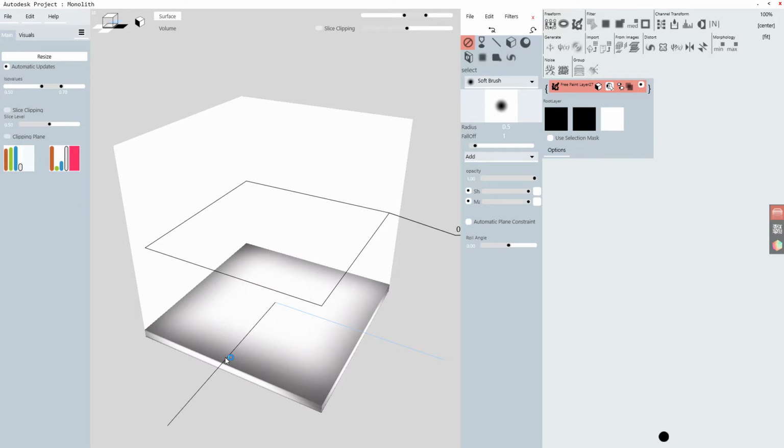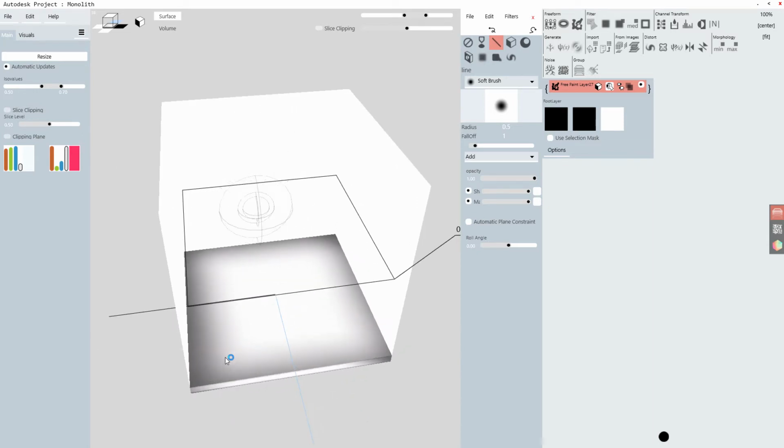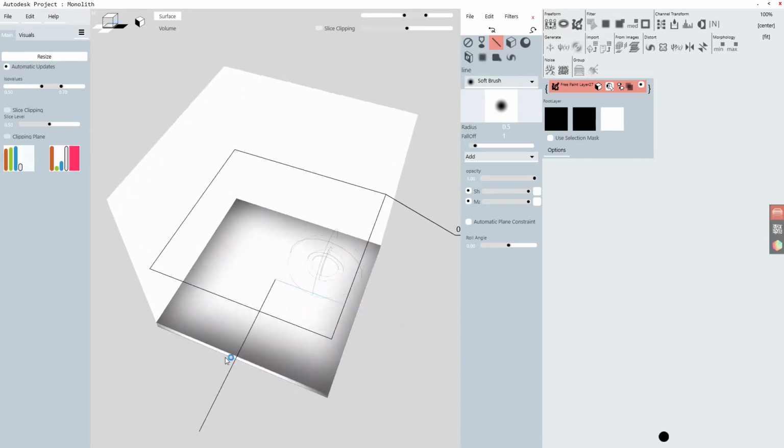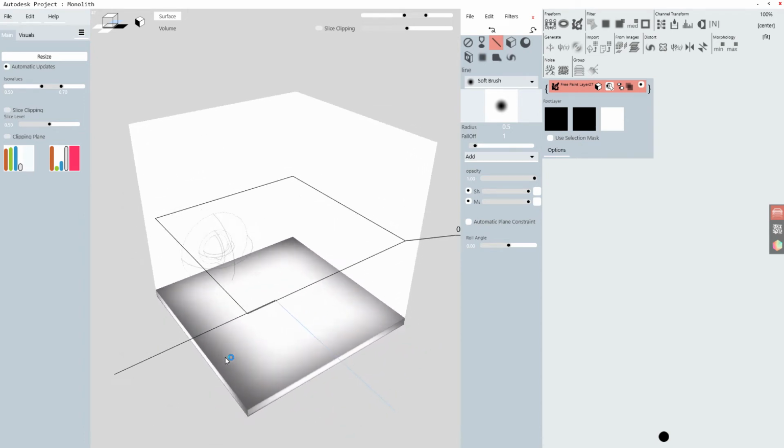The interesting way this works is that it projects your mouse in the three-dimensional view onto the existing surfaces. So to orient yourself, when I click the line, for example, to know where you're drawing, if I put it here, it's projecting over the floor plane. So I click, and now I'm moving a line from that point to wherever point I project now.